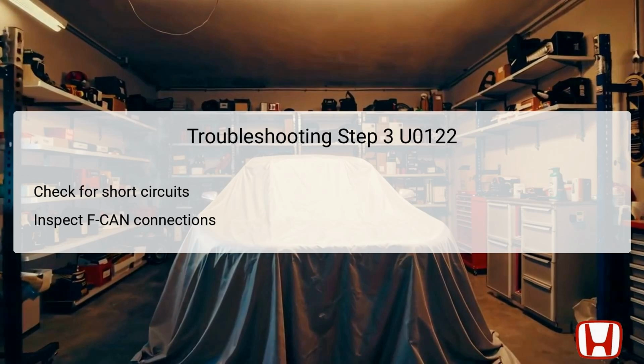VSA modulator control unit. It's also advisable to inspect connectors along the FCAN circuit, ensuring they are not corroded or damaged. These checks are essential, as merely identifying an open circuit may not be enough. It's important to rule out that the lines are unintentionally grounded. This thorough validation helps in eliminating possible causes of the communication failure.